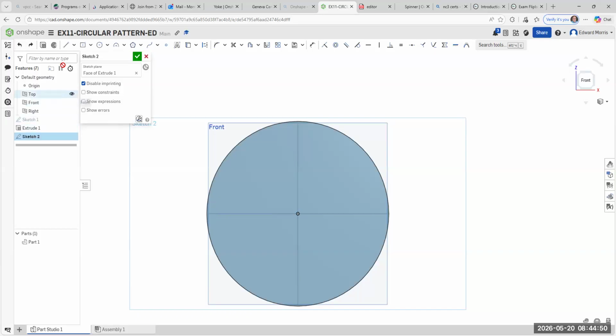So we're still in sketch 2. I went to the rectangle. Look, center point rectangle. I moved here, right? And if you look, you see a little dashed line as you're moving. It means you're in line with the center. Go up to the very top, 12 o'clock position, roughly right there. I still see my dashed line, which means I'm aligned with the center point. Click, drag out an arbitrary rectangle, click. Okay, I got a rectangle here.